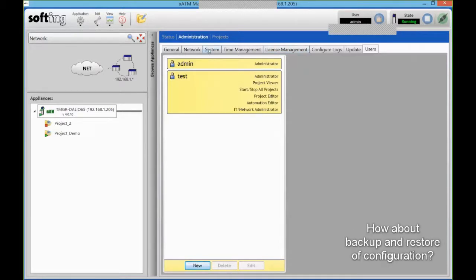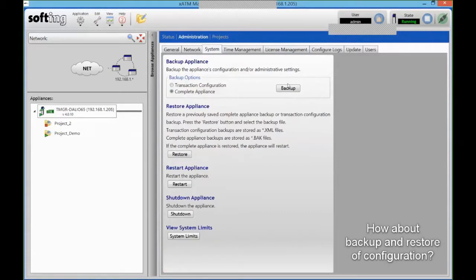In terms of maintenance as well, very similar to a PLC, so you can back up and restore into one single file, so a single operation for the entire configuration of the module. So similar to upload, download to a PLC, and that makes maintenance very easy. So instead, if you have a PC, to bring in a new PC, re-image the OS, maybe the software, reconfigure the software and the connections and all that, this is just a matter of restoring your backup file onto the module, and it restarts where it left off. So very fast and very easy to manage here.